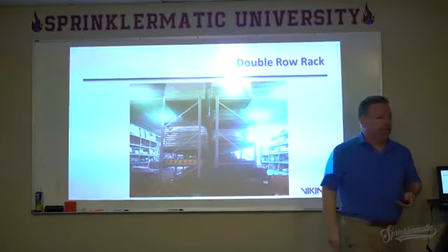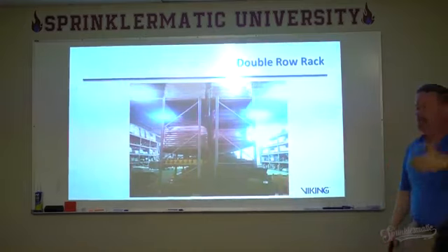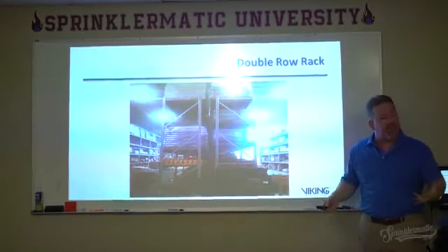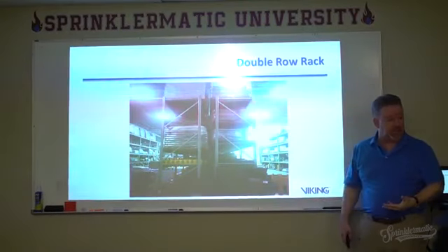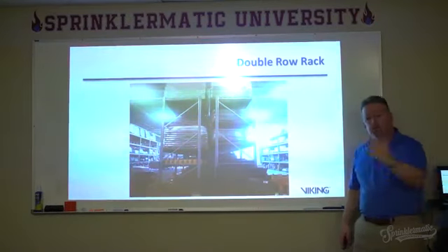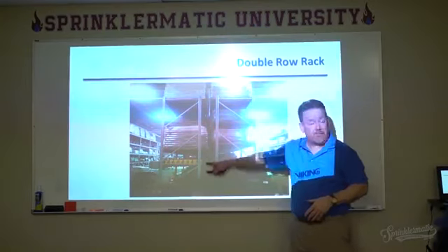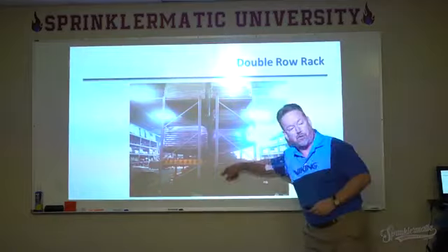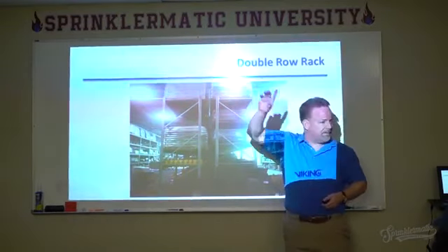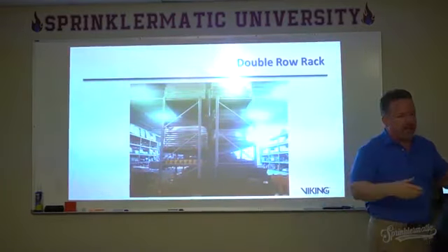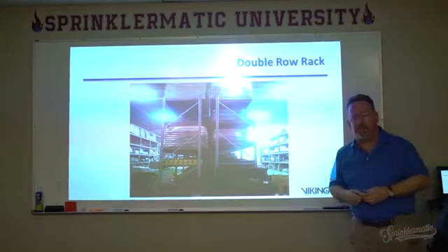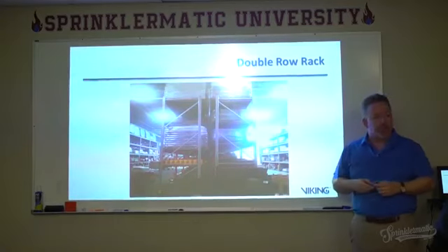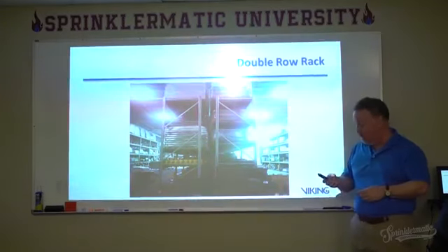it's a bigger challenge to get water to come down and get water back into these spaces. So when we're looking at rack storage, we have to take a look at, okay, are we protecting up at the ceiling line? Is that sufficient? What type of sprinklers are we going to use at the ceiling line? Or do we have to figure out a way to get sprinklers all the way down into the rack itself so that the fire doesn't grow so big down here that by the time it grows to the top of the rack, it's already going to overpower my sprinkler system at the ceiling. So those are two big questions we're asking when it comes to rack storage.